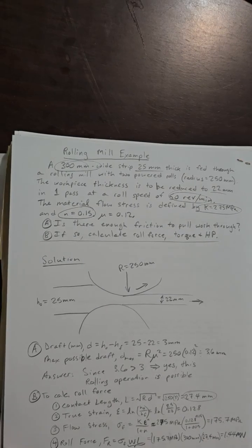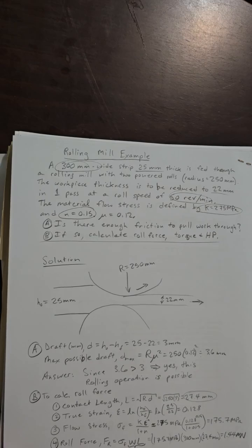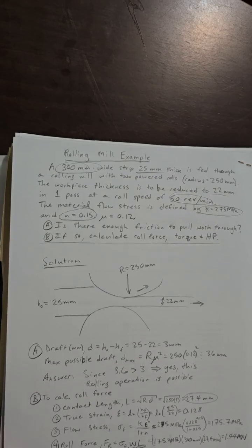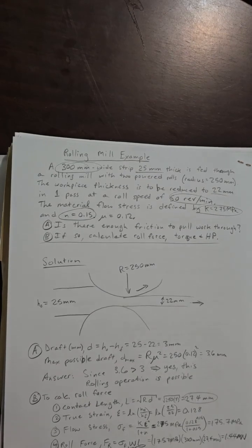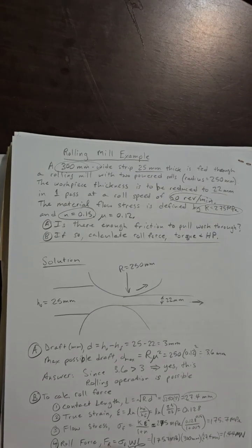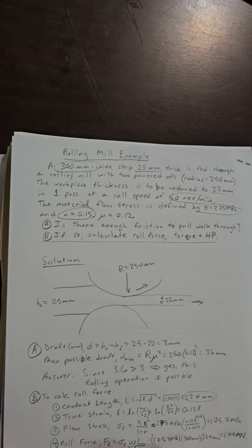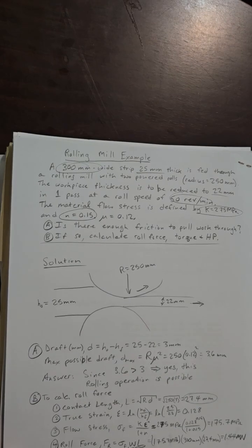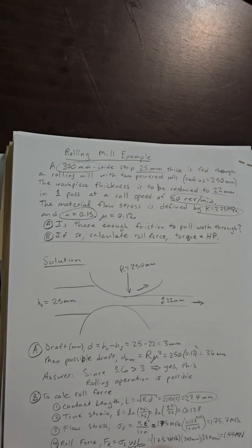Now to convert that from minutes to seconds, we take 12.4 meganewton meters per minute. We want to cancel minutes, so we're going to divide by 60 seconds. We're going to get rid of meganewtons because that's 1,000 kilonewtons. So we get 207 kilonewton meters per second. A newton meter per second is a joule per second, which equals a watt.